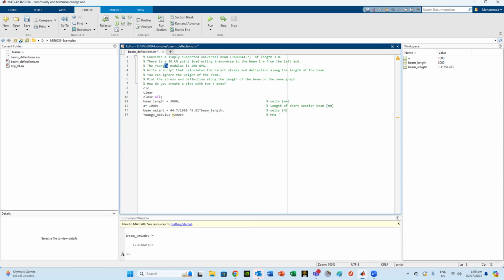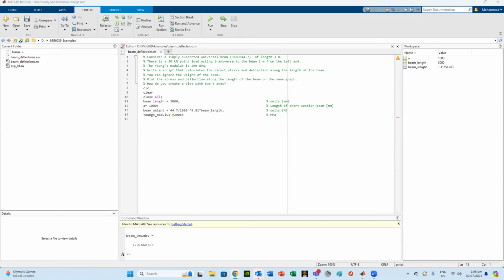So you see, I just make it clear for that beam. That's another information given to us. Now, I will go to the formula sheet because there are a lot of important resources. Steel and tube data could help us to find some of the information. I'll just find that for us because the type of the beam is all available under resources. So remember, it's 360 UB. So I'll search for 360 UB.